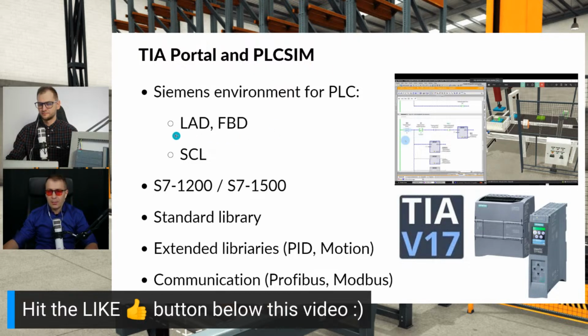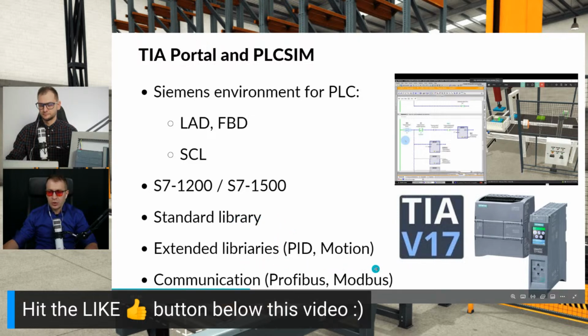You can program in graphical languages like ladder or FBD. Those are the most popular languages for PLCs. And the next one is STL, which is a text-based language. You have a standard library for that and extended libraries like PID and Motion.